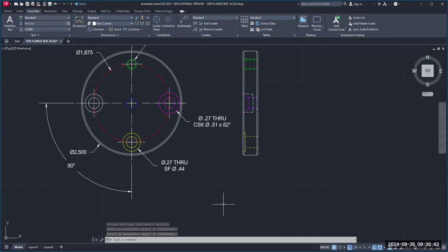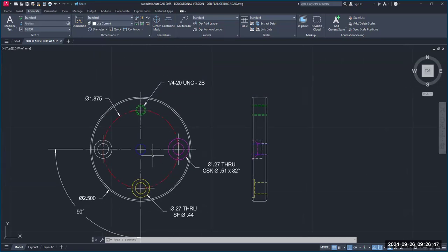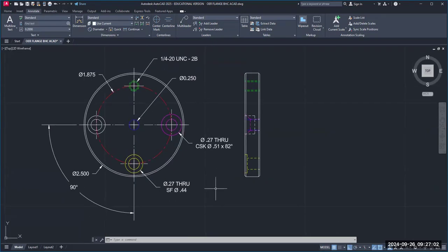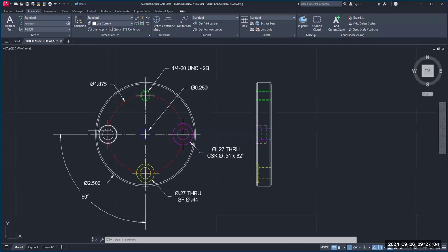All right, so you'll have to practice those. Let's see what I've got. I still got to do this hole here. This one's easy. Look, you just click on diameter and drag it up. It's best to drag your dimensions off of the part when possible. All right, now I need to put this one over here. I'm going to go to diameter, click on the outer circle, drag this over, click.